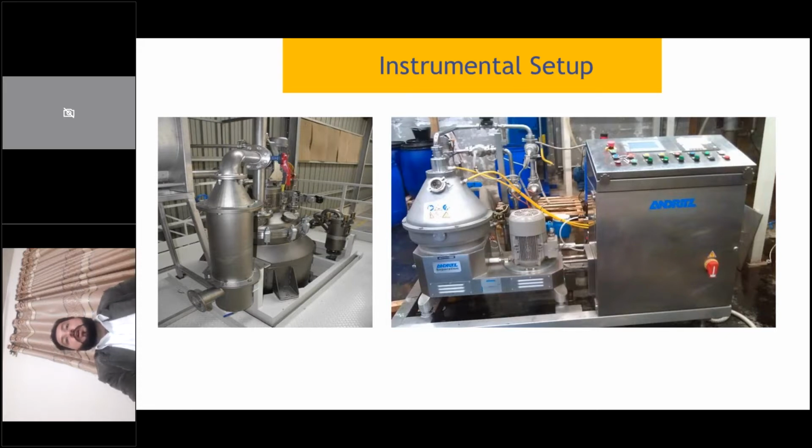Then it is incorporated in various types of polymers as a dispersed phase, and these polymers interact with the cellulose in a very good fashion because both have a similar nature. The cellulose is hydrophilic, and similarly the polymer is hydrophilic, and both have good compatibility. At the end we get very beautiful mechanical properties and other related properties, which we will address in our application part for the composite materials.